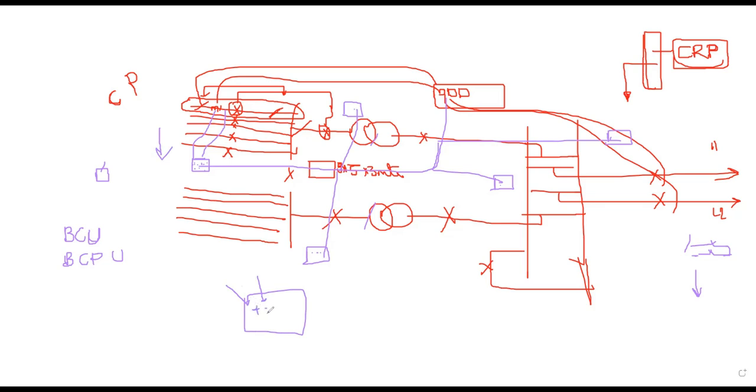If both are AND, then give output. If this flag is high, then it's giving output to the breaker to trip. So, kind of thing, so soft logics. These are soft logics that you can develop in the BCU.